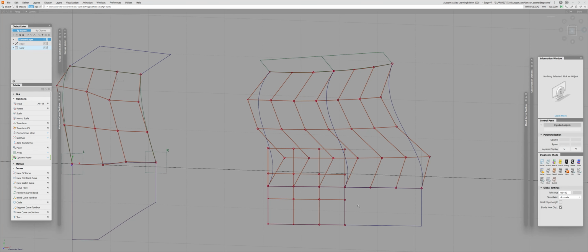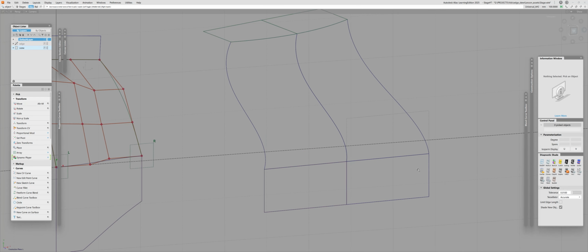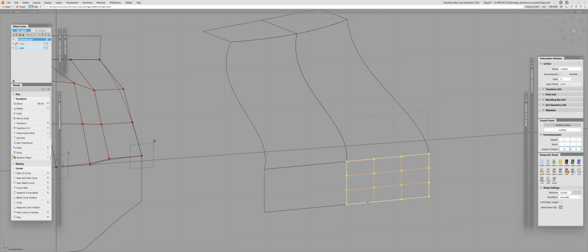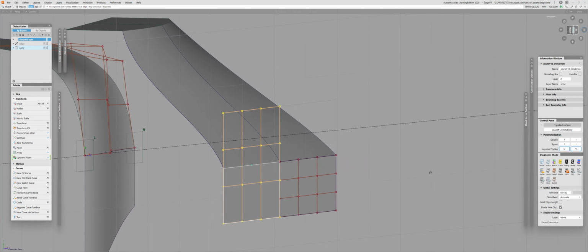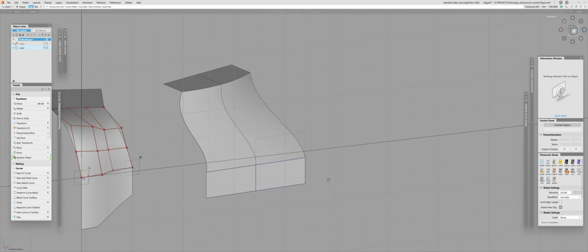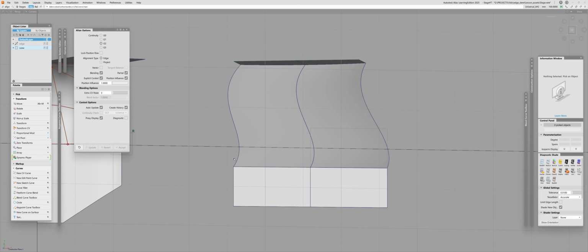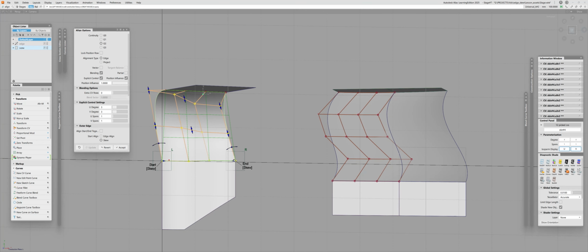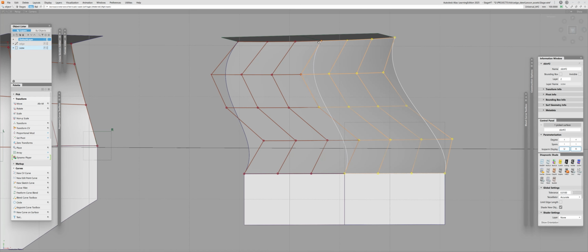On top of that, as you can see, and just to illustrate it again, which is quite important, I have the same surface, but one of them looks the same yet has the natural boundaries. It's not trimmed. It's trim converted, and the other one is not. It is trimmed. So actually, let me show you. This is the surface, and as you can see, it's trimmed. If you don't pay attention and try to align it, maintaining this direction, remember, as we saw here with the inherited boundary, the skew will inherit the boundary, and I assume that now I can align these two pieces and they will match positionally.